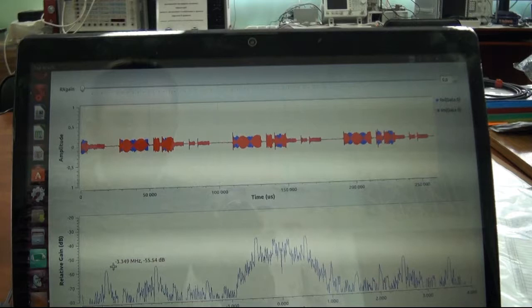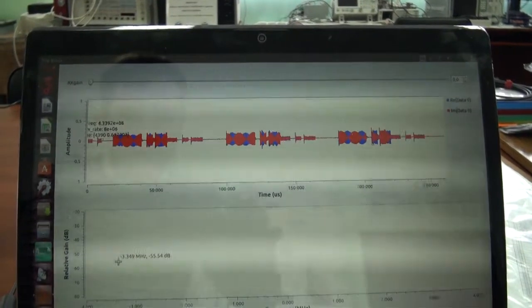Despite the fact that the pause between packets is equal to the packet duration, TDMA is not applied here, because signal transmission in both of the links is conducted asynchronously. GNU Radio shows that power in the second link is slightly less, but the trial was not conducted in an anechoic chamber and the SDR antenna polarization is not matched. The main task here is to show that the signals are really transmitted asynchronously at one frequency.